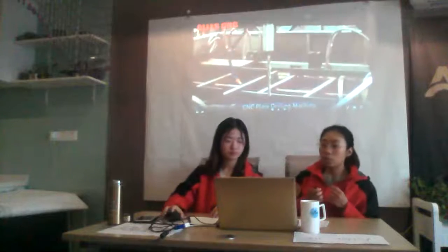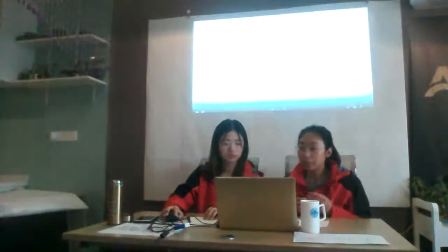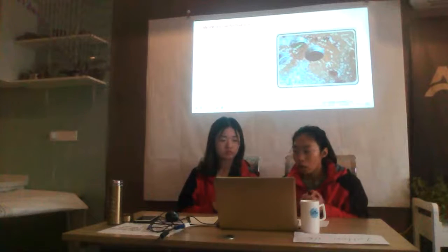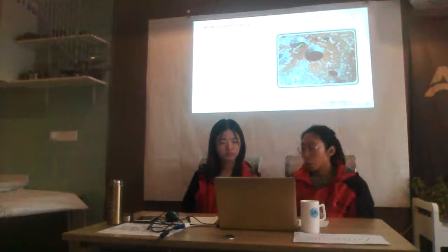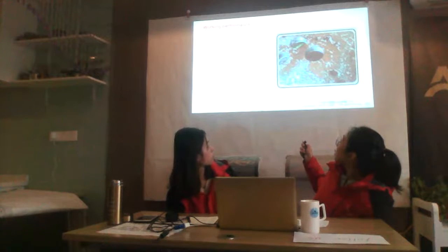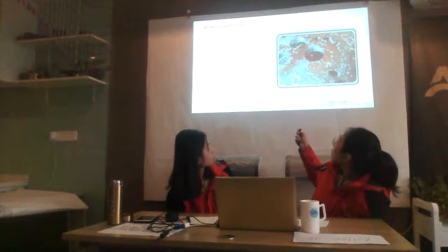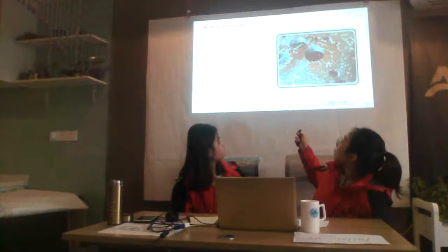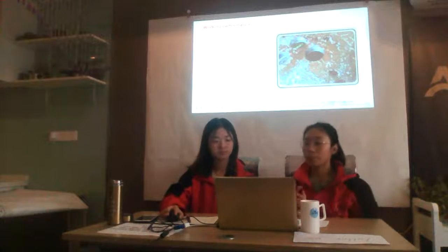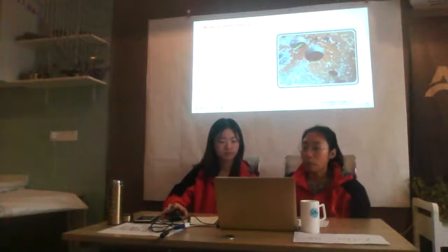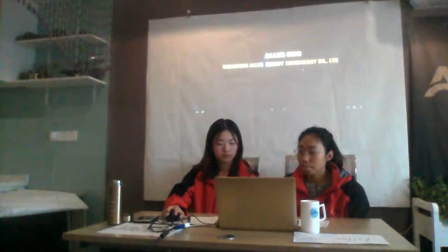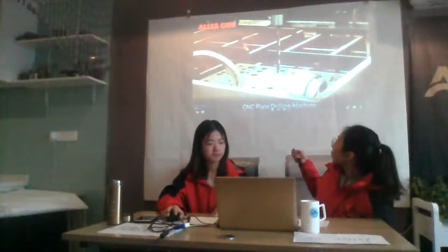This workpiece is slightly rough. And because the standard speed CNC plate drilling machine can only be equipped with two tools, the workpiece surface has some burrs, and the internal of the hole is not very smooth. The internal of the hole is rough. And we have another video to show our customers. Yes, let's show the details.